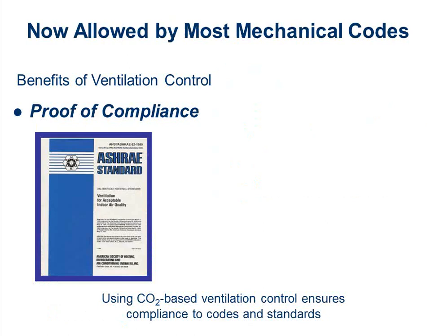So all that stuff happened pretty much in the late 90s, mid 2000s, and that really drove what we did with the standards and codes. Nowadays, demand control ventilation is allowed by just about every mechanical code. In fact, I can't think of a mechanical code that does not allow it in any municipality or state. It's been in ASHRAE 62.1 for years. It was an addendum in 2004. It's been in the permanent standard since 2006.